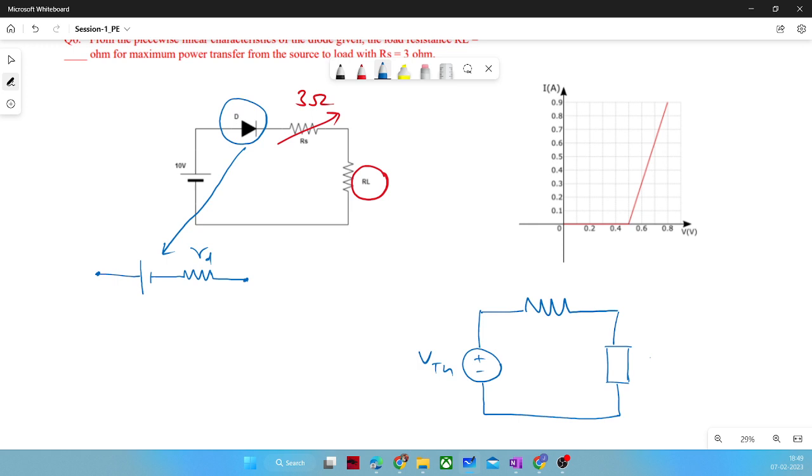So this is your load resistance and this is your Thevenin resistance. Thevenin resistance generally combines all the resistances in the circuit, an equivalent kind of resistance. If you derive it, some differentiation operations are applied in general circuits, and based on that a condition is concluded that when RL is equal to RTH, then your maximum power will be transferred from source side to load side.